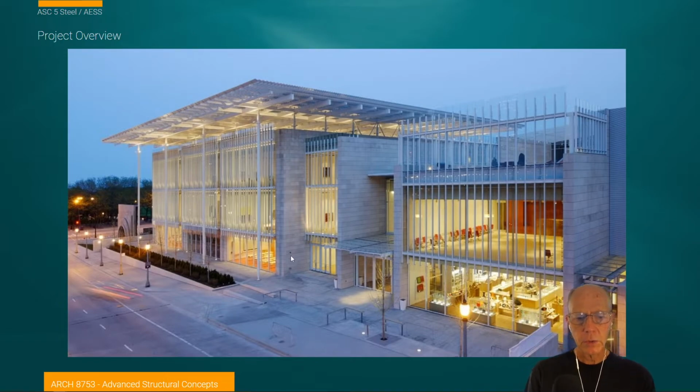So once again, that's what that column area is. I've already mentioned the idea of trying to calculate the tributary area on this. And we have this idea of what kind of beam structures are needed here to support the load. I point your attention to what we just discussed about the tributary area at the end columns not needing to have as large a column.